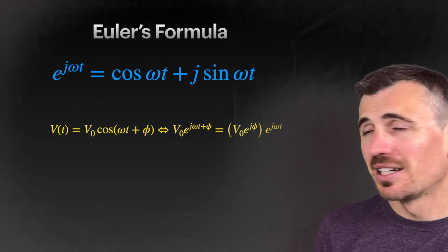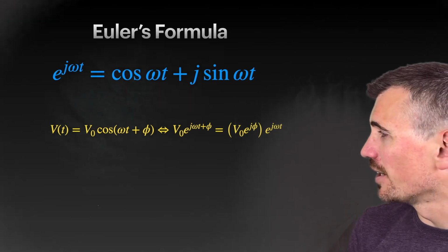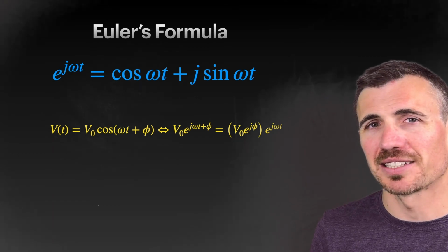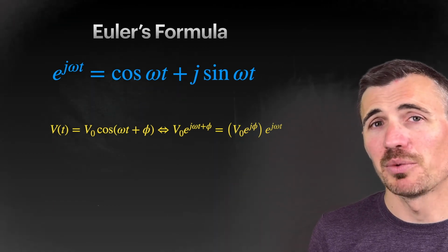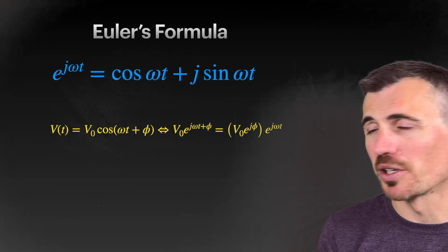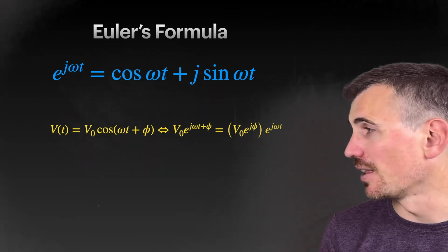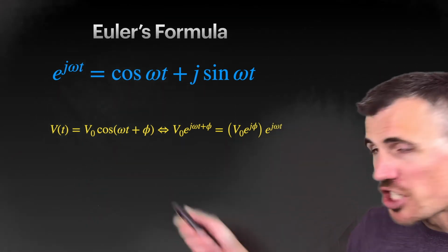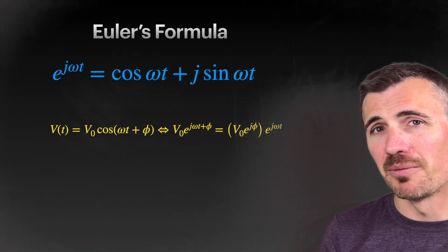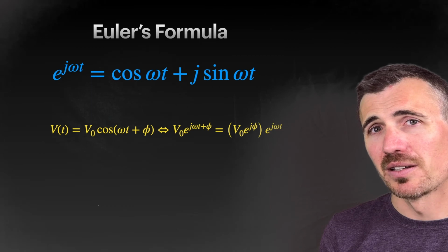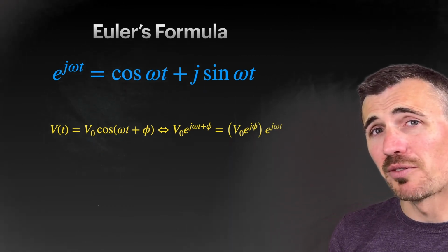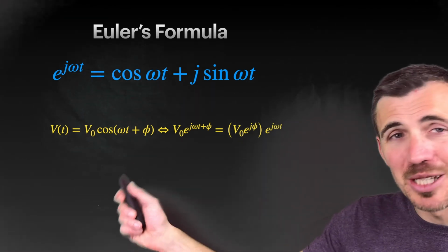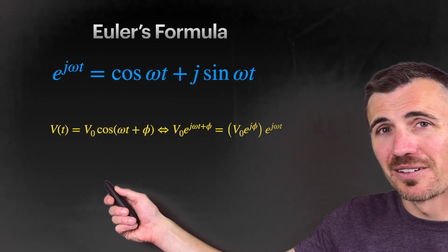The common trick is to represent your voltage as a complex exponential, as we've done here, and then in the end, take the real or the imaginary part. If you want to take the real part, because that sounds more reasonable, that's fine. We just, as a result, get the cosine quadrature. So we're looking at the cosine quadrature of the component by taking the real part. The imaginary part gives us the sine quadrature. In fact, we can take any projection of this voltage that's varying with time, and we're going to get a realistic quantity from it. But to be honest, in this course at least, we often don't even bother taking the real part. We just have our complex voltage, and we divide it by our complex resistance, and we get the complex current. And we leave it complex.